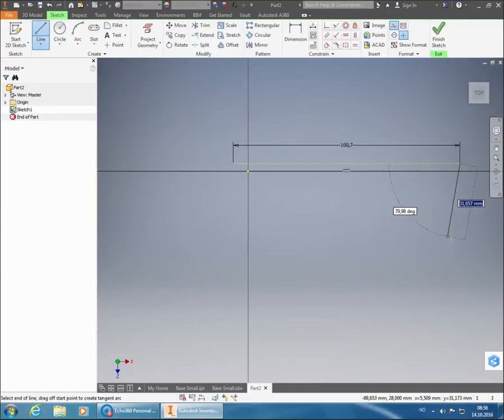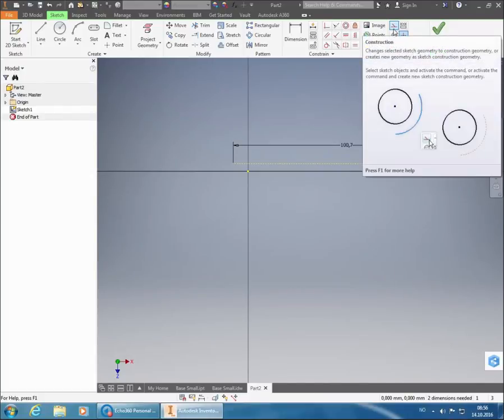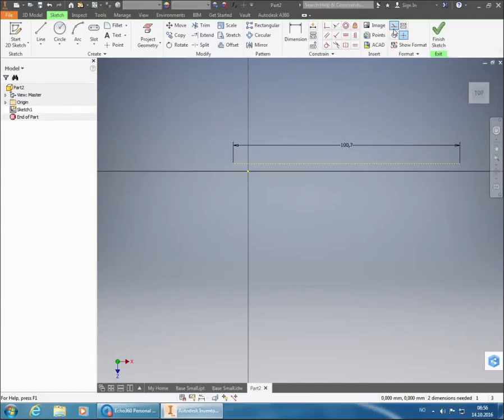Once I've placed the line, then I'm done with construction line and the line function for now. So I'm going to hit escape to escape the line function. Now the line function isn't marked blue anymore. And I have to go up to the construction line option, and I have to click it so that it's not blue anymore there either.